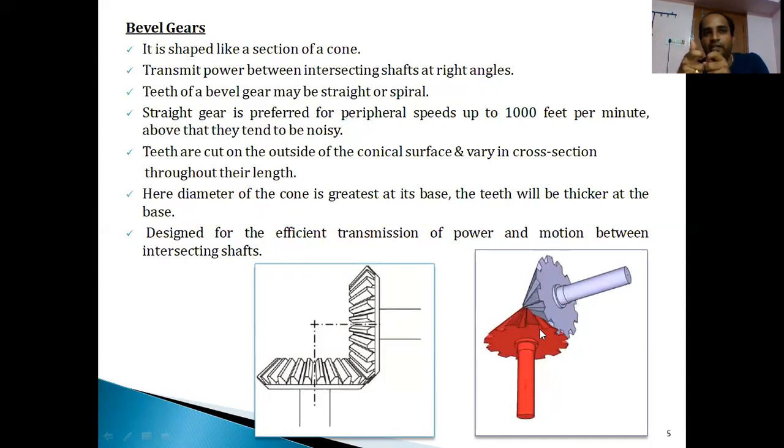The chuck key and the drill spindle intersect, perpendicular to one another, and they are nothing but bevel gears, because they act as an efficient means of transmission. That is why when you fix the chuck, you rotate in the vertical direction, while the drill in the hole moves in the horizontal direction. So both are perpendicular to one another. These are some of the points with respect to bevel gears.